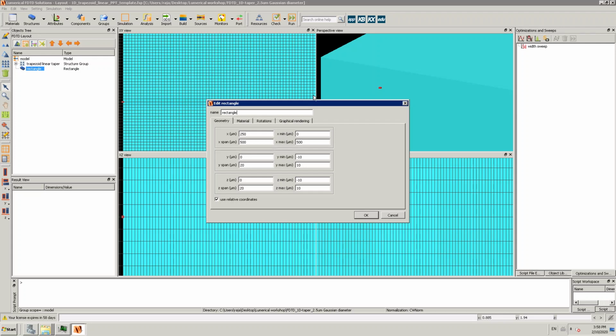I'm sorry, I had a question actually. Your taper is having this kind of triangle shape, but it also has some weird profile. I've seen you make a triangle from cubes, and there is some sort of discretization. So what's the rule of thumb for this? Like how should you discretize your structure in order to not have numerical artifacts?